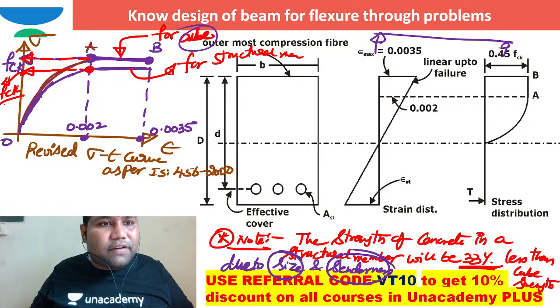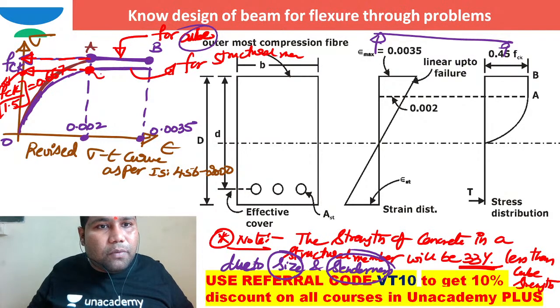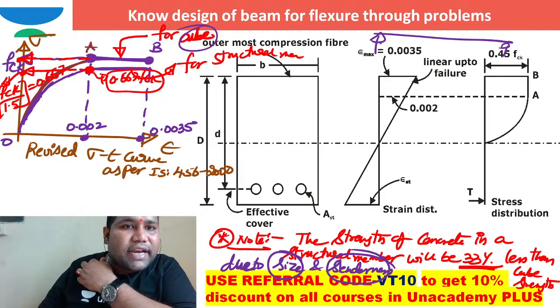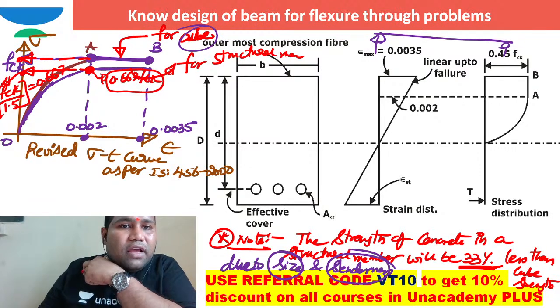The factor of safety for shape and size effect is 1.5. So this is nothing but 0.667 FCK. This point is 0.667 FCK. When compared to FCK, what is the percentage drop in strength for the structural member?